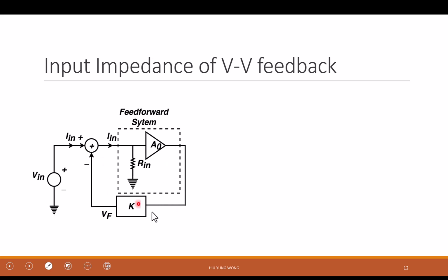No, you are the amplifier. I'm talking about you are the amplifier and the input is voltage. What are you doing? The input is voltage. Input is what you're trying to sense, right? So it is voltage. So if you're sensing voltage, what impedance should it be if it's ideal? Infinite. So you want to make it large, right? So going through all this, maybe your cheat sheet already tells you the answer. That is fine, but you need to find a way to memorize it or to check it, right?